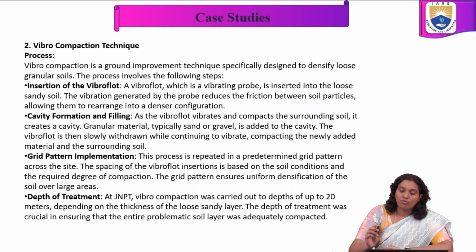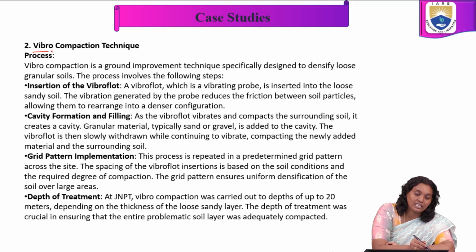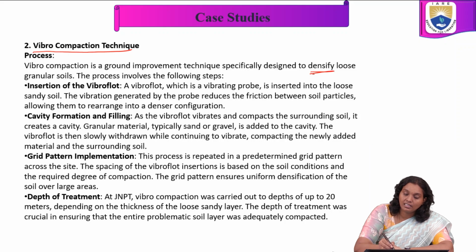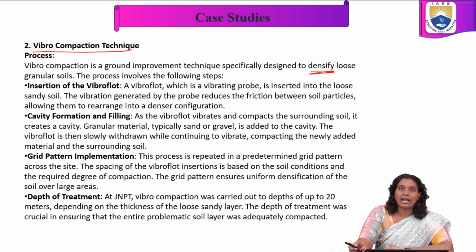In this, the technique we adopted is the Vibro Compaction technique. It is a ground improvement technique specially designed to densify loose granular soil. So here it is for densifying loose granular soils. The process involves insertion of the vibro float, cavity formation and filling, grid pattern implementation, and depth of treatment. These are the major steps involved in this.